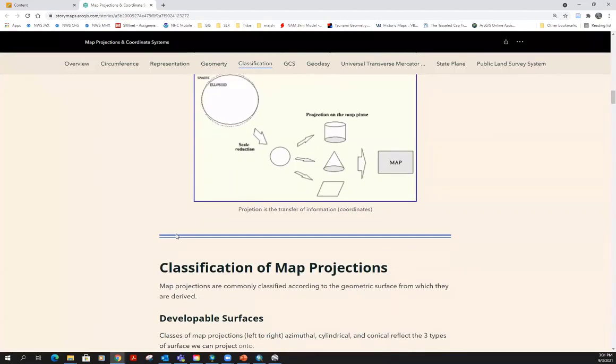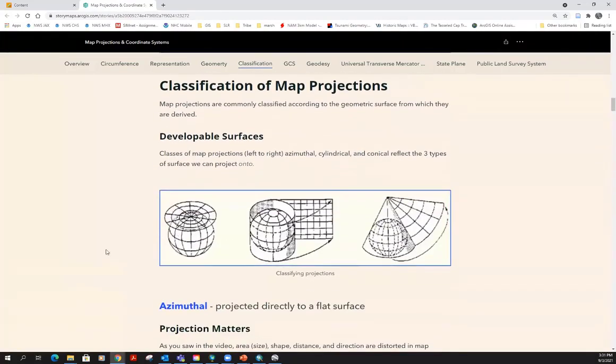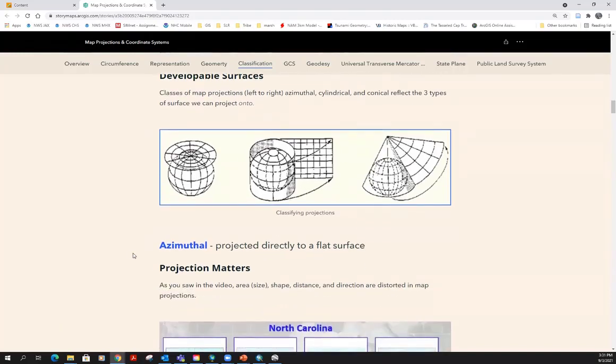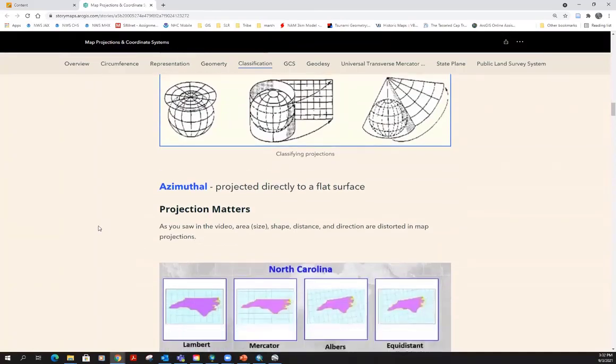And then you can measure different types of coordinates on it. Here's a graphic that better illustrates, maybe it's an old one, a planar projection, what's called a cylindrical projection, and what's called a conic projection. Depending on the type of distortion that you want to minimize or the accuracy you want to maximize, it affects your choice of developable surface. This is something we spend quite a bit of time on in cartography, computer cartography, and GIS classes.